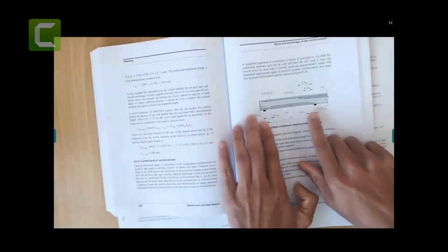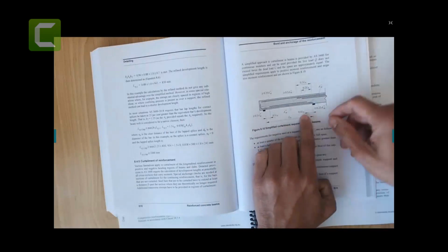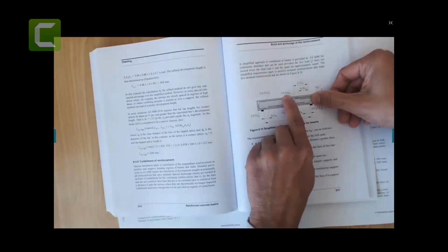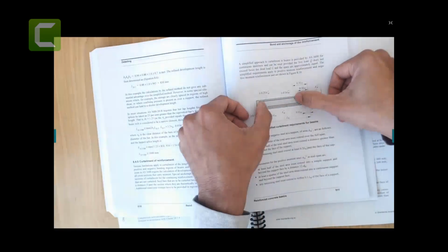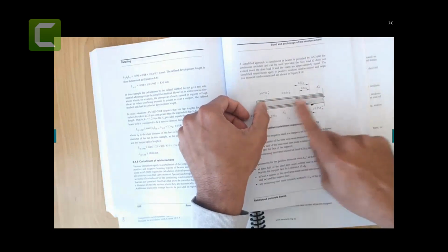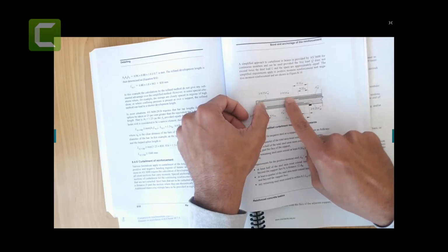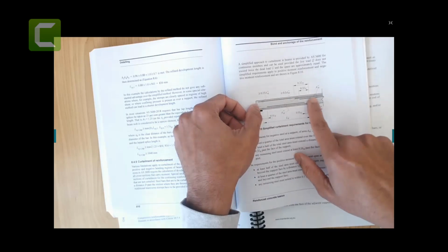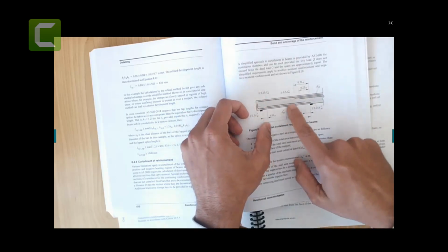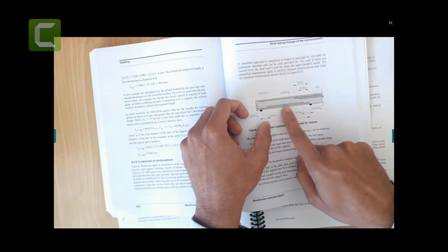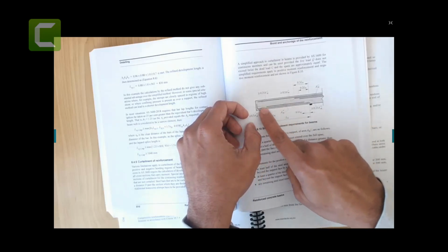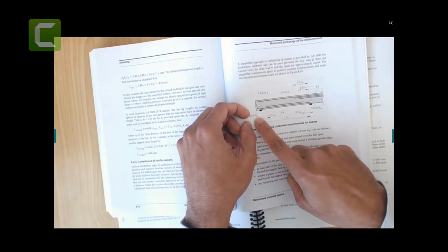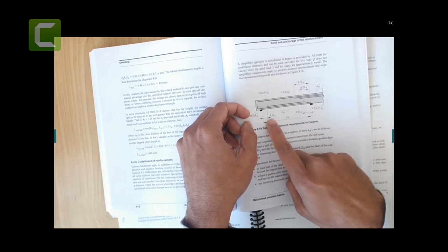So basically it says that okay, the bending moment is very high here. So in that case, you can just provide extra 0.2 ln up to here for greater than 0.5 AST. You can cut it off here as well because your bending moment is reducing. Then 0.3 ln and you can provide this 0.5 AST in here. In this region, you can just cut it off, just a quarter of your total AST. For the positive, you can provide the full here because you have maximum bending moment here. But as you go past here, you have much less bending moment. So you have provision of just reducing your bars by 50% at both ends from this length 0.1 ln.